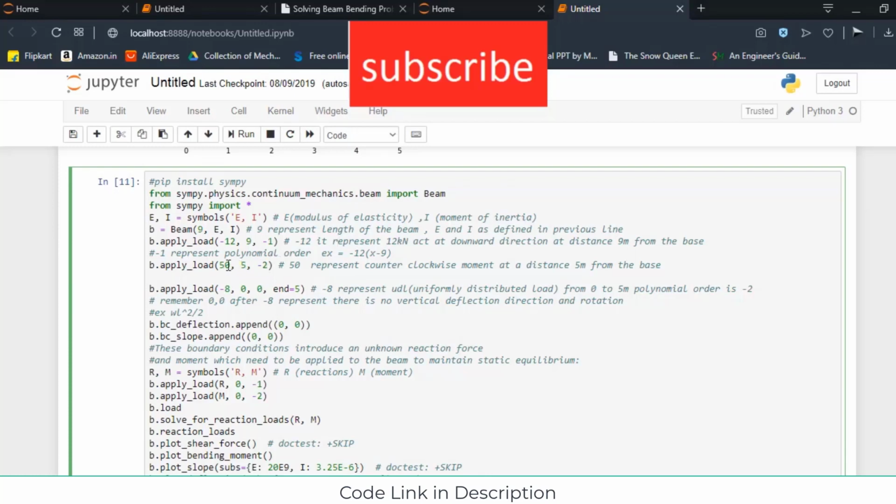50 5 minus 2. Here 50 kN meter is our counterclockwise moment at distance 5, and its polynomial is minus 2. Here I am applying the third load, that is minus 8 0, 0. Basically 0, 0 represents that there is no deflection on the vertical axis, and it starts from 0 and ends at 5, and it is a uniformly distributed load, okay. Remember, for a uniformly distributed load you declare 4 variables instead of 3, as you can see in the previous loads.